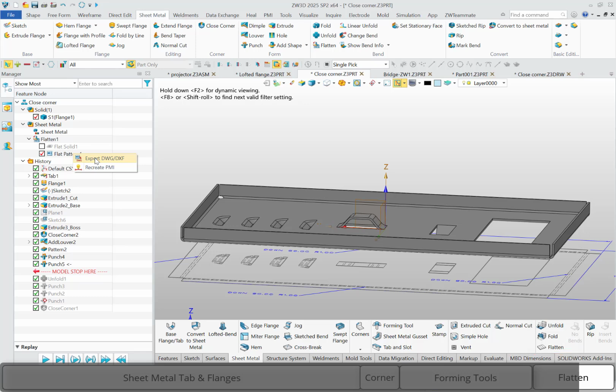In the end of the video, I'd like to share a small software skill to convert imported sheet metal parts and generate a flat pattern for manufacturing. The process includes recognizing sheet metal features, converting the model, and unfolding it for detailed drawings. Let's go through the steps.